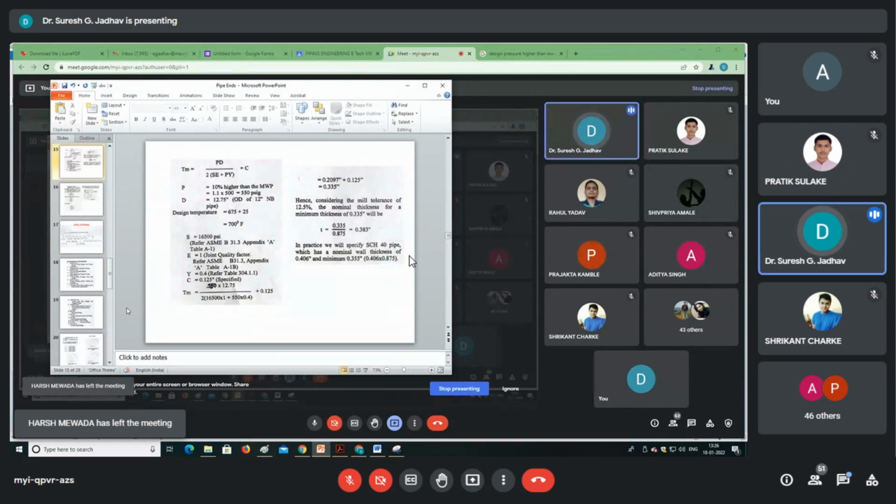We are studying low temperature and pressure application services. We are not considering high temperature and high pressure services. If it is high pressure and high temperature, then definitely we consider 25% for pressure as well as temperature. Is it okay? Yes, sir.